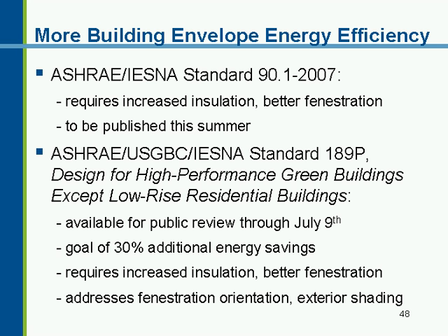In terms of looking ahead and working on green buildings, and we hope you're all working on greener buildings, the next version of Standard 90.1, the 2007 version, will have some increased insulation requirements, better fenestration requirements, and I've highlighted some of those for you. And that should be published later this summer.